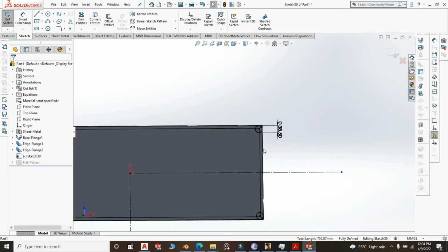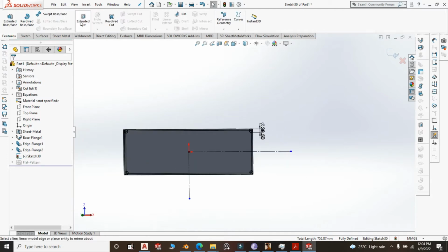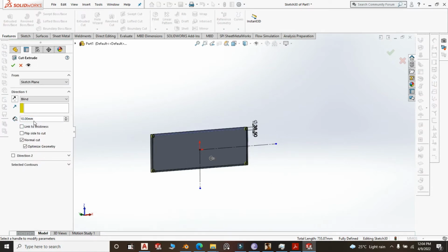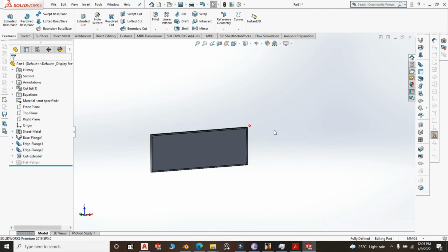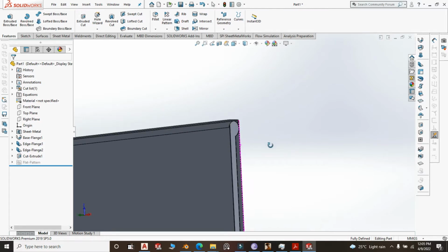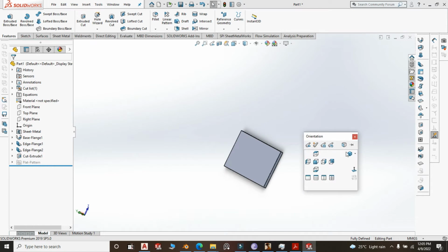We want to make a notch on this bend, on the 15mm bend. So extrude and cut it by even 10mm, 5mm is still okay. There. So now your circular leg will go through this, and this is where you are going to do your welding, right around it. You don't want the welding to be seen from the top. Right, now the top is done.